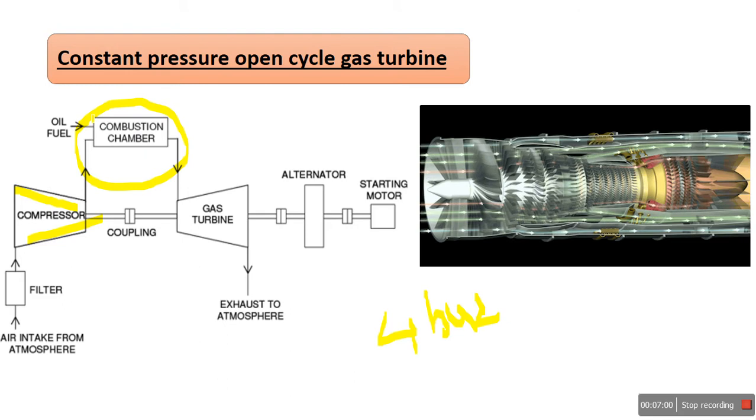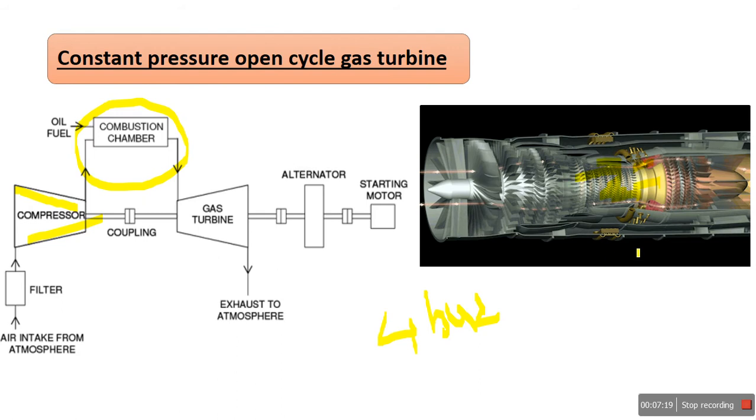Okay, the burner injects fuel into the combustion chamber. Now this is a very important term. Now I discuss the compressed air. Suppose 100% of air is supplied to the CC. Out of that, only 25% of the air, if you see here in this zone, is supplied to the CC, and the remaining 75% of air flows over the outer casing, in the annular space between the inner casing and outer casing. Only 25% of air is utilized for the burning purpose, and the remaining 75% of air is used to cool the CC.